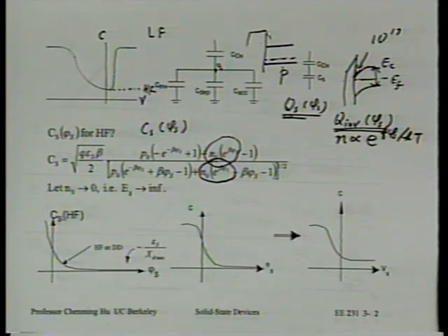But interestingly, these days, for engineering purposes, we rarely deal with MOS capacitors. We always deal with MOS transistors. Even when we want to study a capacitor, we just take a transistor and ground the source and drain to the substrate and call that a capacitor. That's typically the way engineers work today. Not that we cannot get our hands on capacitors, but we prefer not to deal with them, because with capacitors we have to deal with the question of where electrons come from.